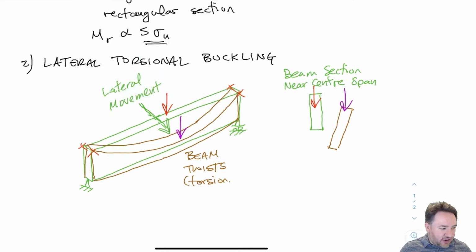So there's my best artist's rendition of a beam twisting and lateral torsional buckling. And so you can see that the bottom of the beam over here twists sideways a bit, but really predominantly it's the top of the beam that's going over. And the reason that it buckles is because, as we said, when we bend a beam, the bottom is in tension and the top is in compression. So basically what's happening is, since the top half of this beam is in compression, it can buckle just like a column in compression can buckle. So we have a buckling phenomenon happening, but just on the top.